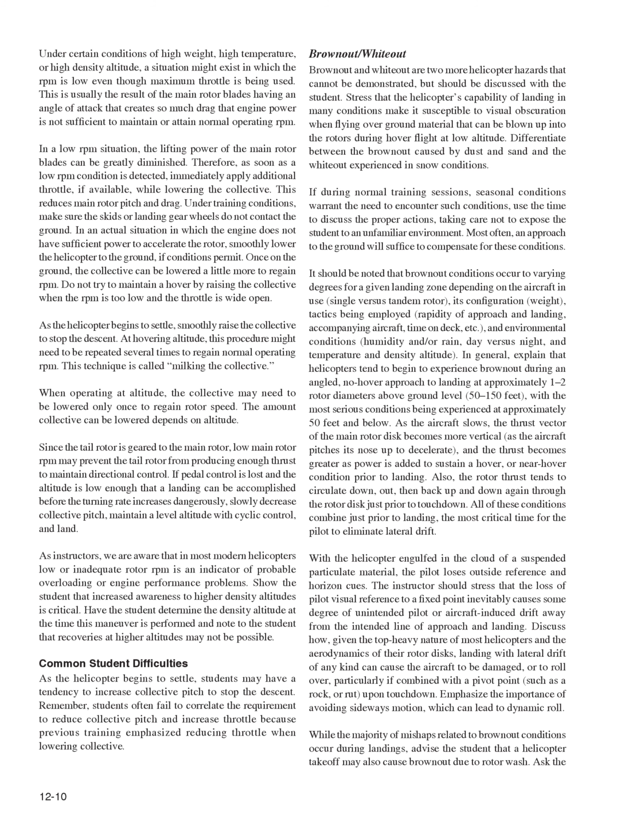As instructors, we are aware that in most modern helicopters low or inadequate rotor RPM is an indicator of probable overloading or engine performance problems. Show the student that increased awareness of higher density altitudes is critical. Have the student determine the density altitude at the time this maneuver is performed, and note to the student that recoveries at higher altitudes may not be possible.